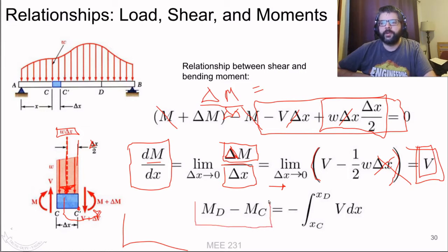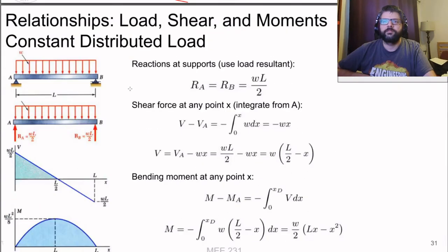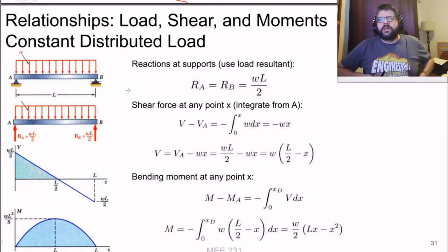And likewise, we can always find the change in moment from one point to another by integrating our v delta x, by integrating our shear diagram from those two points. So there are a few things that we can look at.